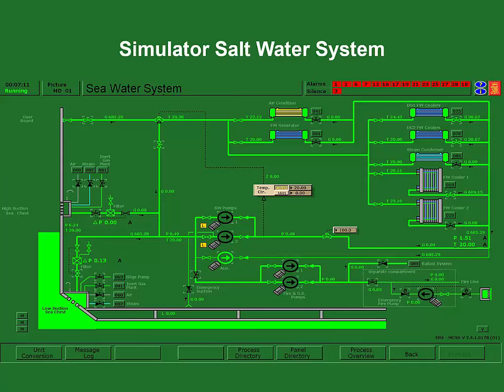So typically, when the vessel is unloaded, it's going to sit much higher in the water, and that high suction will be out of the water. Then the other problem is when you are fully loaded, then that sea suction is very deep in the water, and that changes the pressure dramatically. So most tankers will switch from a low sea suction to a high sea suction, really dependent on their loading condition. So just realize that.